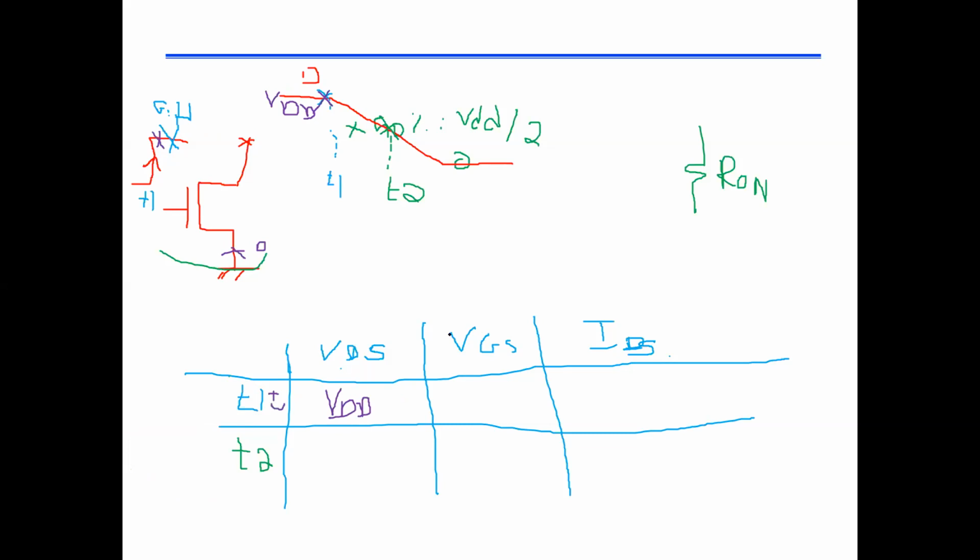Okay, and since the VGS made a rising edge at T1 with an infinite slope, this means VGS has flipped to VDD and stayed at VDD. So gate voltage or input, we always assume that effective immediately it has switched, it flipped.